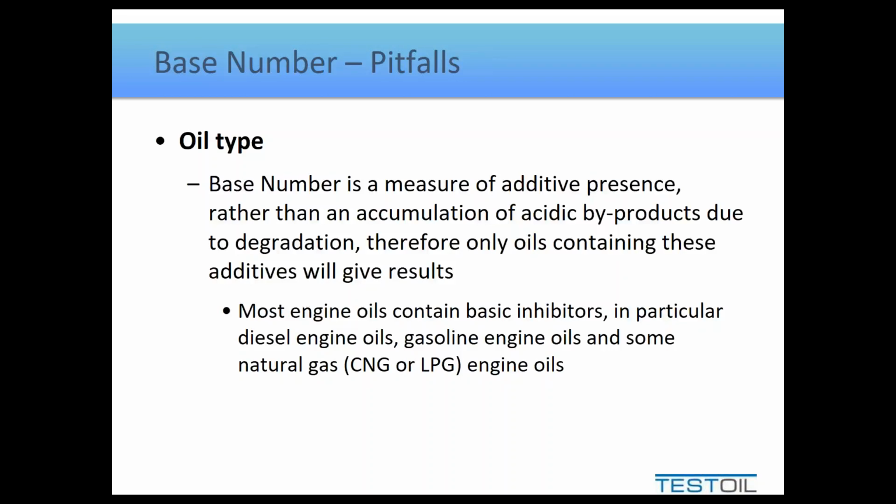It's either that the discharge into the reservoir is too high above the surface. It could be that the suction is too close to the surface, meaning that generally speaking the oil level within the tank is too low and it could suck air in. So whether you're discharging from too high and mixing air in, or you're sucking air in through the suction because the level's too low, that's one mechanism. Another one would be an air leak on the suction side of a pump. That's another great way of detecting a significant foaming problem. Use a smoke pen or something like that and see if you can tell if there's an air leak, because obviously nothing's leaking out, it's actually air leaking in.